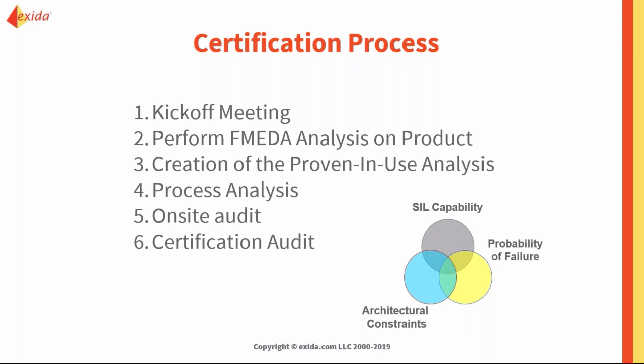The proven in use analysis looks at both the field failures and the shipments and returns and sees how comparable they are to the predicted failure rates in the FMEDA. If one is way different than the other, we like to investigate and find out why.